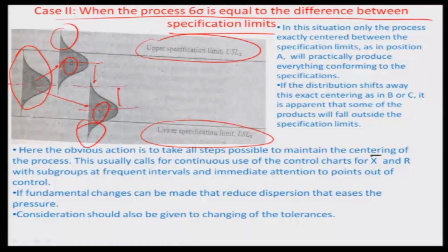So this is how you read, based on the upper and lower specification limits, the various control aspects of the chart. So another possibility could be in this case to revise the tolerance and see if it works out for this particular process, because obviously it is a very tight situation where the process mean and spread are just about good enough to be accommodated within the upper and lower limits, and a little bit of decontrol also leads to outruns and many rejects, as you can see here.